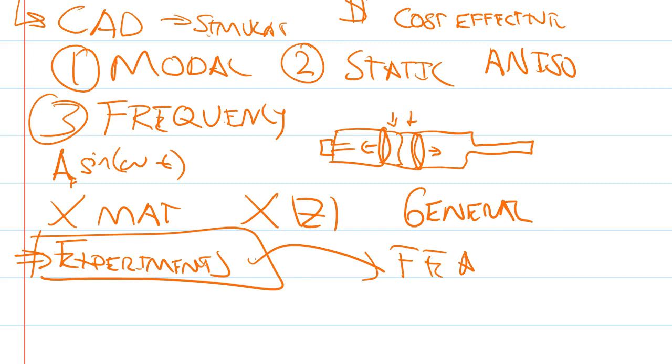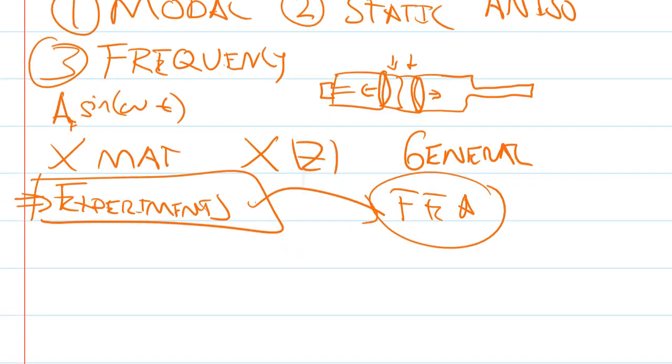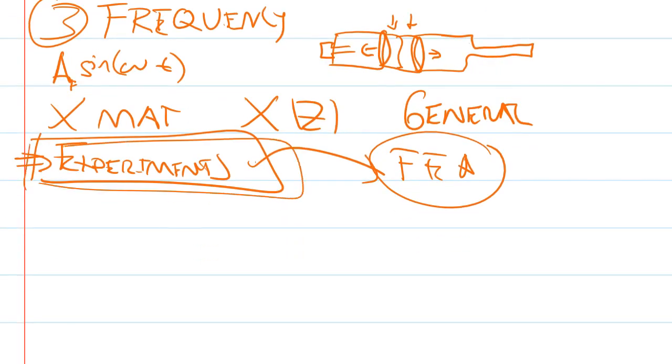The way I would do it, the way I do it, is you use FEA to come up with your first prototype, your first idea, so you're not just drawing out what you think, or 100% relying on predicate devices or just equations. You would first make sure nominally the device works as intended, and once you understand that it works as intended, then you go ahead and produce the device for the experiment. If you find it not working, use FEA to understand why it's not working, and experiments obviously. And then after you have found a working device, you can go back to FEA and further optimize it.